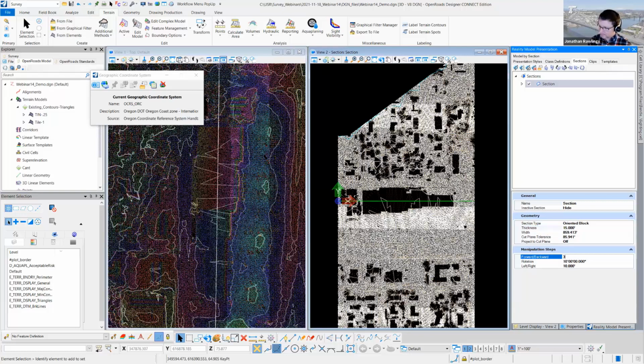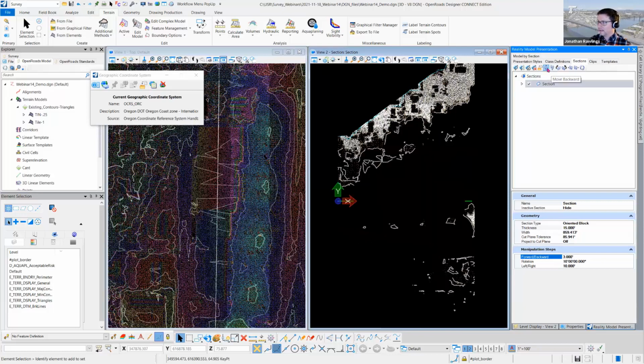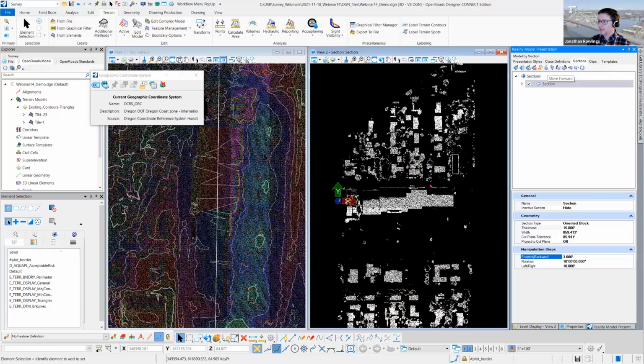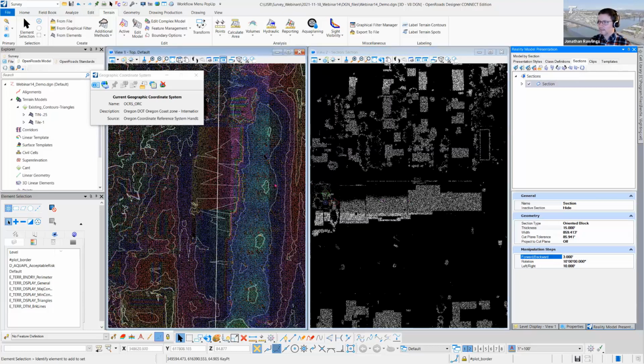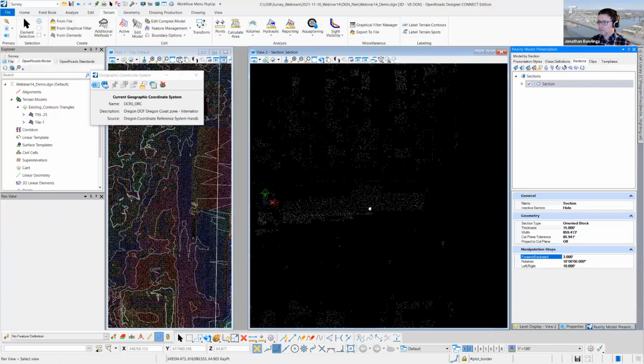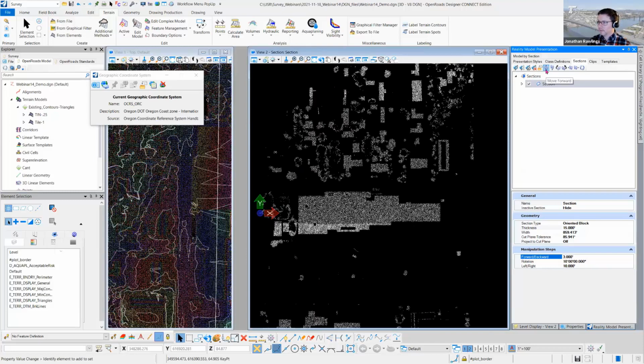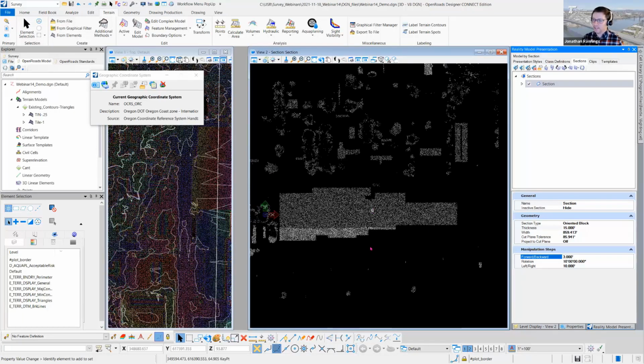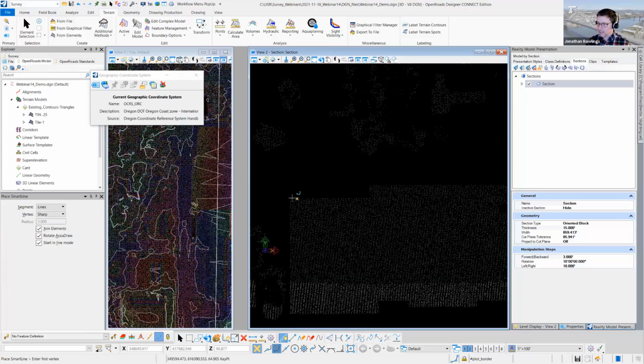And I'm going to go forward and back 3 feet. And I'm just going to move this point cloud. I think I'm going the wrong way. So let me go up with that till I get to the building. So I'm starting to see, this is the building right here. And I'm starting to see that roof line come into my cross section. Looks like we're there. Go back one more. Yeah. So I can just take a line, snap to that point cloud, draw an outline of this building.